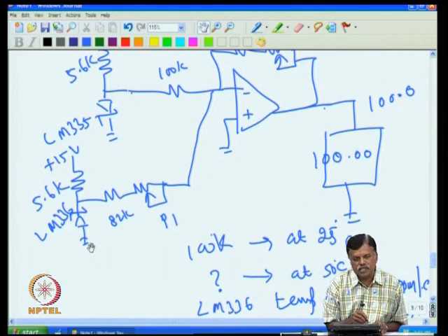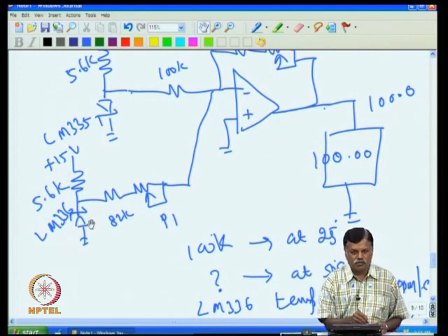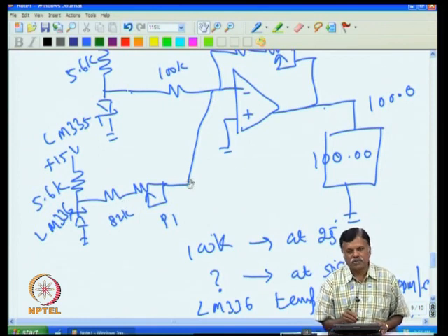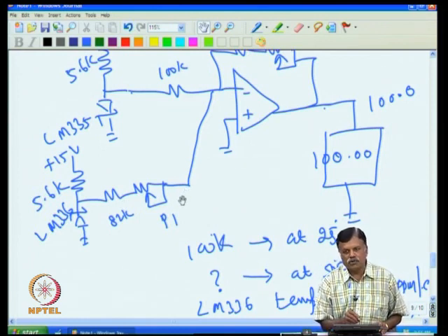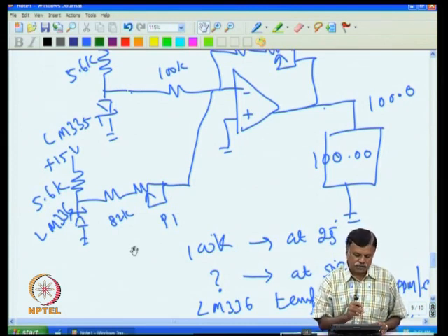So obviously for industrial measurement or for industrial grade equipment, I have to assume that the temperature changes from minus 20 degree to plus 80 degree, because at noon, if the instrument is mounted in the open field and you go and touch it, that instrument will be very hot. So you have to take it as an industrial grade working environment up to 80 degree.